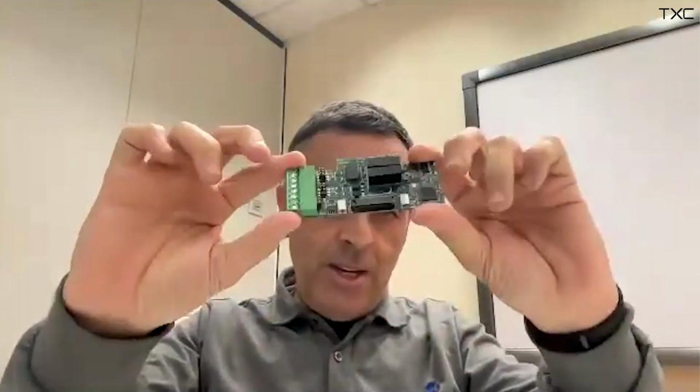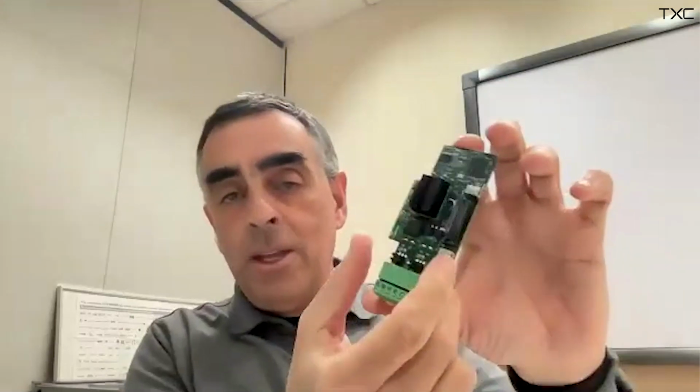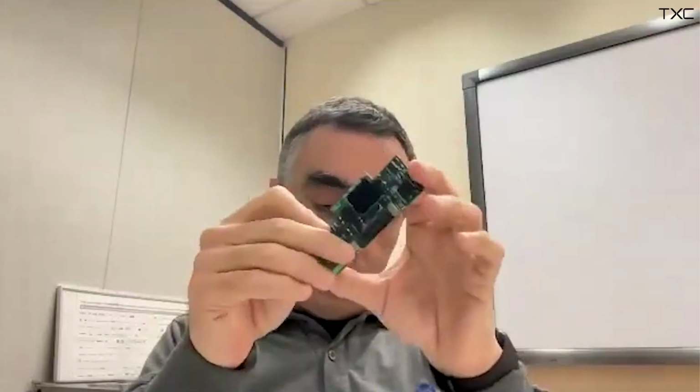The expansion boards are like this, a tiny format. It's a proprietary format that we have developed to fit into this kind of enclosure, basically. So it takes advantage of the way a standard DIN rail is done. The format is proprietary, although everything that goes through the connector here are standard buses. Basically, the communication from the motherboard, we can call it, to the expansion boards is done by USB, I2C, SPI, and GPIO.